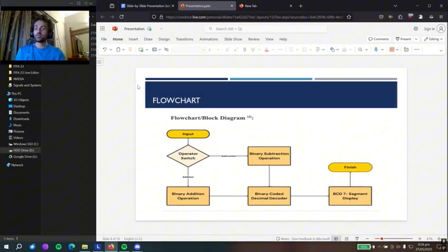The adder/subtractor module uses full adder logic with XOR gates to support conditional subtraction with 2's complement logic. We manually derived the logic for each bit addition, taking carry in and carry out propagation into account to ensure arithmetic correctness. For subtraction, we implemented inversion and addition of 1 to follow 2's complement rules. While it's a relatively resource-intensive process, we optimized it using simplification techniques to reduce redundancy.